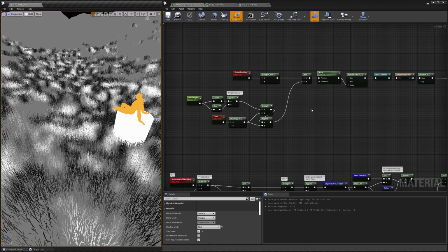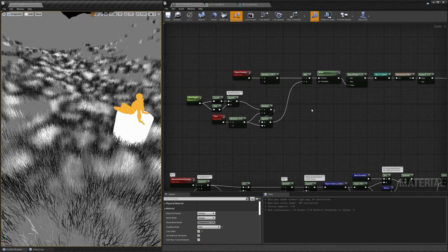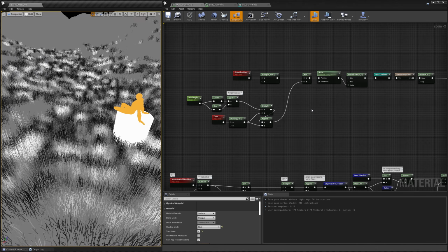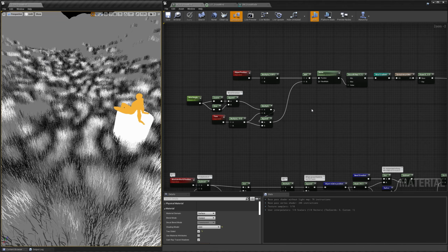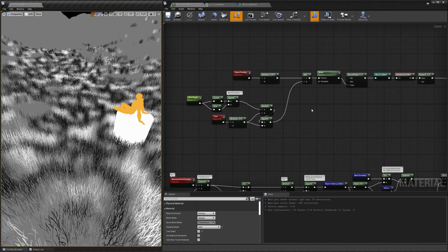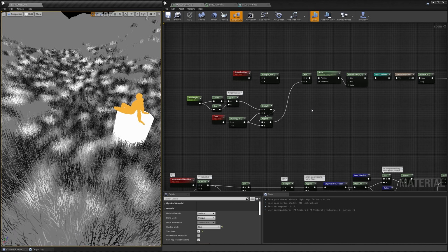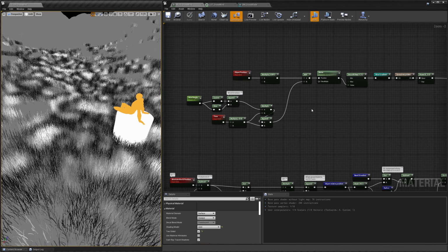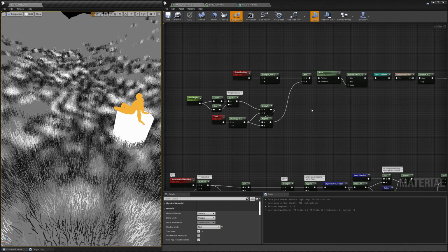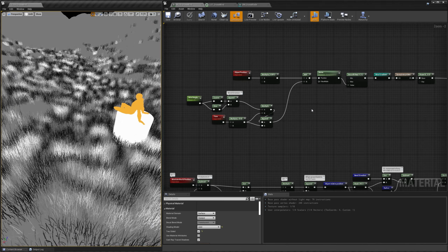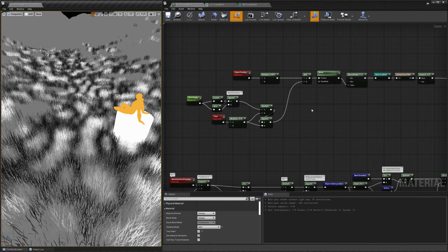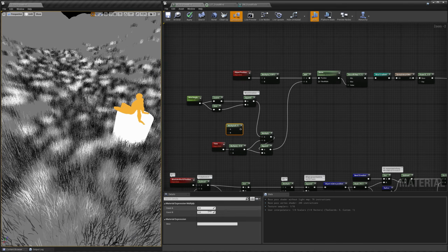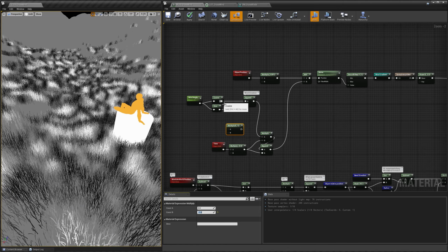Since the wind angle can be potentially set with any value, we have to find a way that will always work. We can't just stretch it, let's say, along the x or y axis. To do that, we can use the same approach we already implemented to our bending. Use the wind direction and the wind tangent to transform the object position xy components to a new base. Let's calculate the wind tangent vector by rotating by 90 degrees the wind direction.